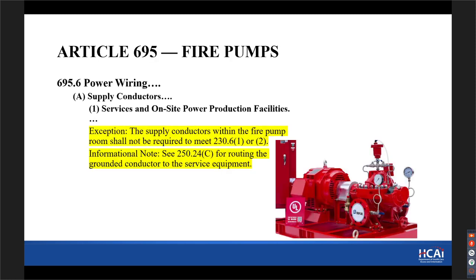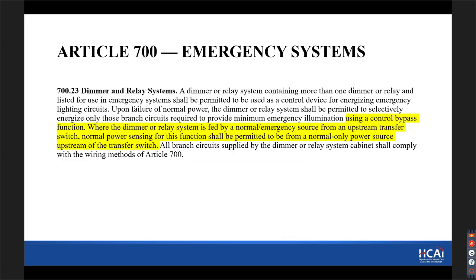Fire pumps. Essentially it gives the exception for the 2-hour protection of the fire pump wiring, so that inside the room, which is a 2-hour rated room that houses the fire pump, that's not a requirement.